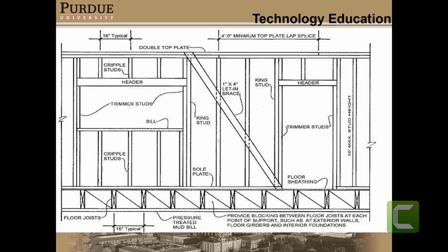If you can imagine a 1.5-inch piece of lumber on its side plus 1.5 inches, which is 3 inches, and you put a 1/2-inch board in between, nail them, and you can use them as headers. The rule of thumb for headers is for every foot of span, you need 1 inch of header. For example, let's say you have a 12-foot opening. You need a 2x12. That's simply the easiest way to remember it.